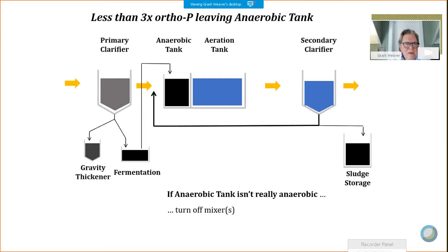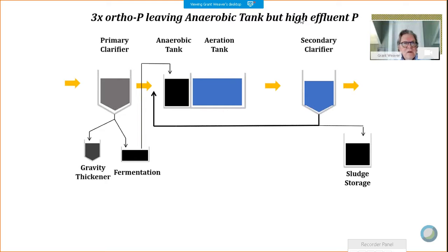Okay, that's going to mix it a little bit, but not so much as mechanical mixers. So now we have a more anaerobic zone, which will bolster its ability to create volatile fatty acids, so VFAs, and it'll make for a stronger anaerobic fermenting environment, which will help the bacteria that eat the volatile fatty acids consume them.